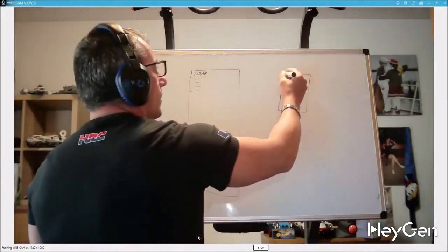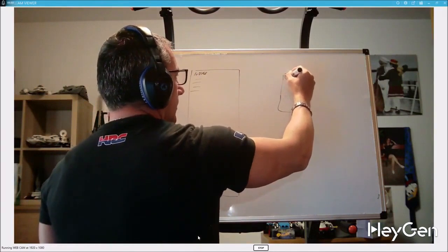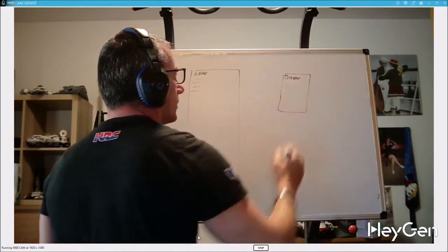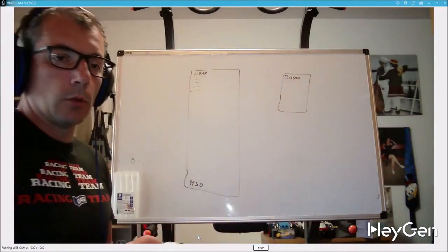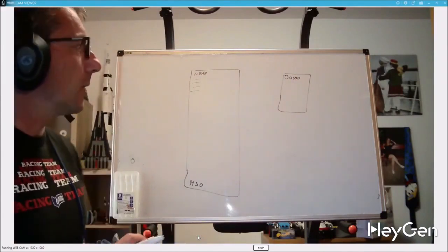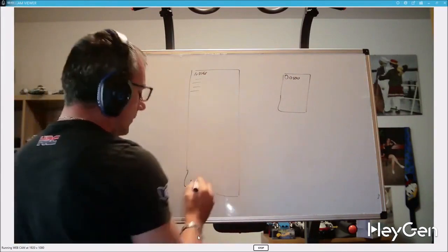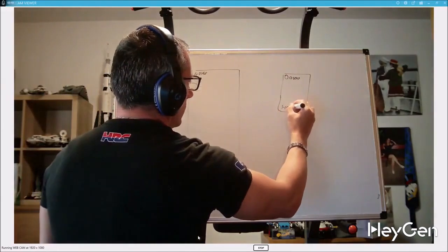Some, but not all, ask for a specific name. FANUC, for example, requires an O followed by 4 digits, at least. The older FANUCs, the current ones, probably the very latest, can also be called anything you like. What really matters is to differentiate them at the end, with M99.